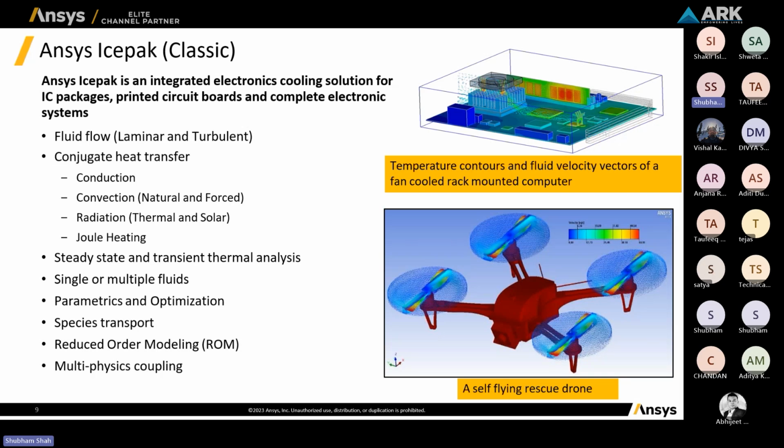There are two ways to perform this kind of simulation. One is that you manually change the fan RPM and perform the individual simulations. Let's say you are varying the RPM of the fan from 50 RPM, 100 RPM, 150 RPM. In the first way, you can go with 50 RPM, mesh it, and set up the full case. Then you replicate this case, change the RPM, and perform your meshing, and again go with the solution part. This is one way.